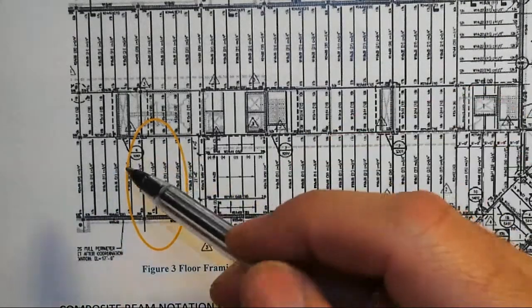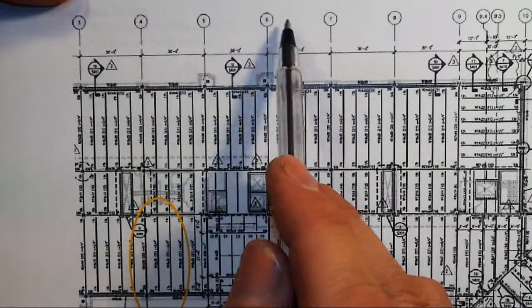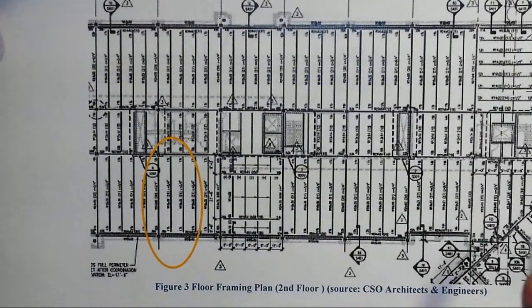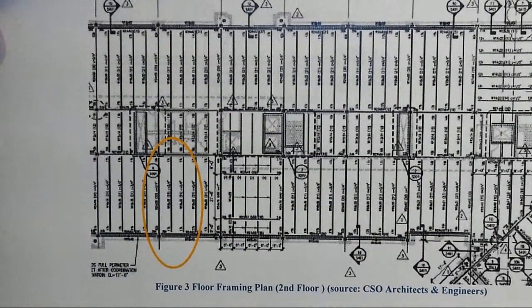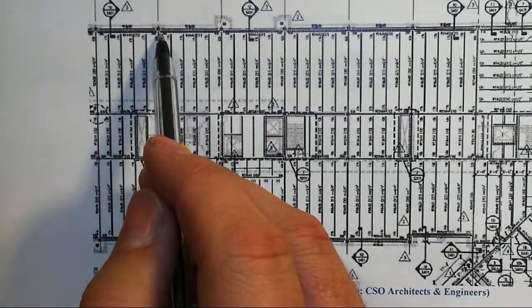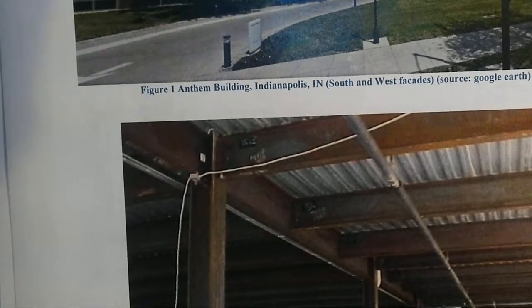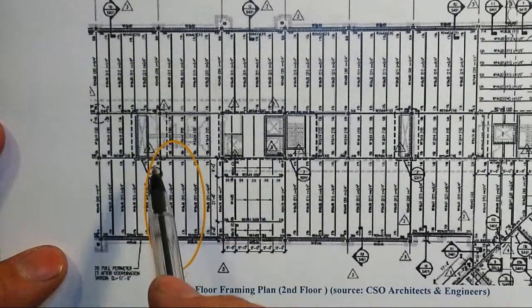And so these columns, you can figure out the columns by location. These little circles indicate column lines, and where column lines intersect, such as here, here, here, here, we've got 4 of those going the other way. Those are the locations of the columns, and those are, in this case, a little square because those columns are not solid steel squares. They're hollow tubes, but rectangular in cross section, so that's why their symbol was drawn that way, as you see through here.